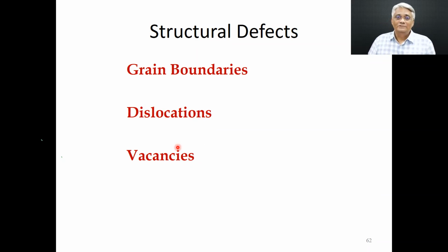In today's technology, the physics of defects is very interesting. We call it the physics of defects. There's so much to understand about the formation of defects, how to control these defects. Point defects cannot be avoided because you cannot have perfect crystals. Grain boundaries can be avoided by transforming bulk materials into thin films and single crystals. Okay.